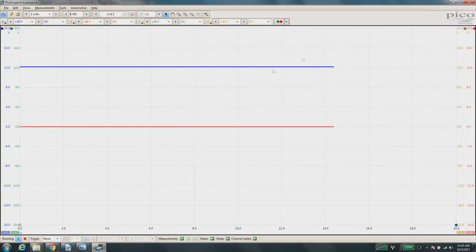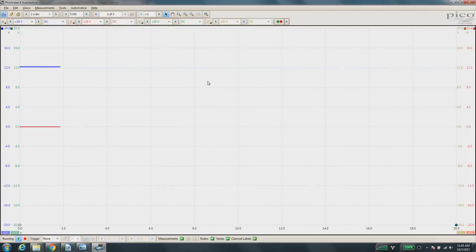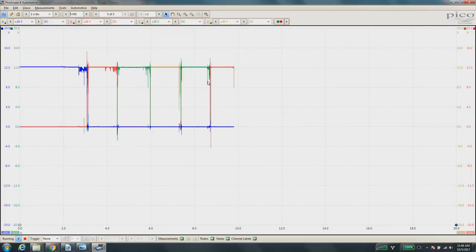All right, so as soon as this refreshes, I'm going to have Jim cycle us through all the gears. So we're on a fresh page. All right, Jim, go ahead. Go through the gears. Reverse, neutral, drive, neutral, reverse, back to park. Okay? So it looks like a mess right now. Some of you who know what you're looking at might already see some issues. But what I see here is we sit 12 volts high for park, reverse, neutral, and drive, and then back to neutral, reverse, and park.